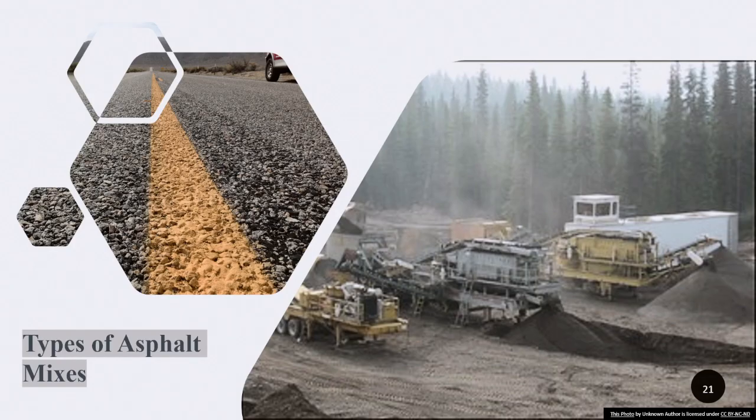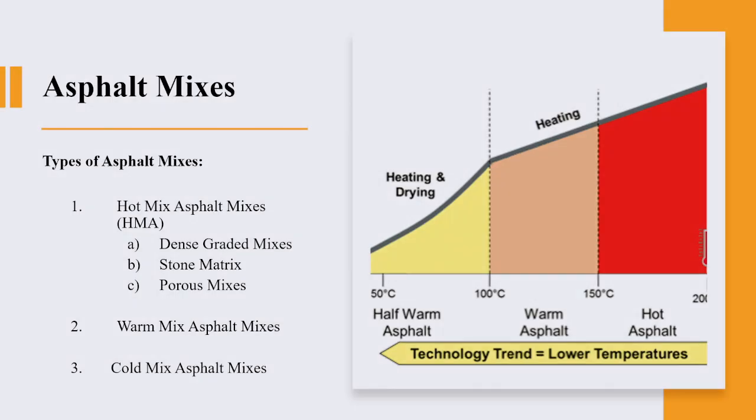But when it comes to types of asphalt, it's pretty standard all over the globe, with a little bit of unique designs for what we call the stone matrix asphalt in the US, and I think Canadians are using the same because of the amount of trade going back and forth between the US. There is a NAFTA, the North American Free Trade Agreement, where you have thousands of truckers going back and forth between the US and Canada with hundreds of thousands of tons of cargo. So in order to fight this, they had to develop the stone matrix asphalt, or the SMA, which is a type of the hot mix asphalt, as we see, with different type of gradation for the coarse aggregate.